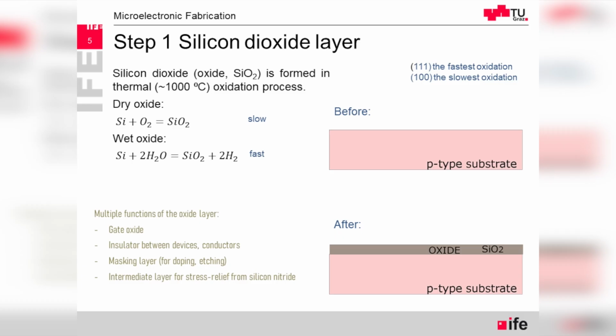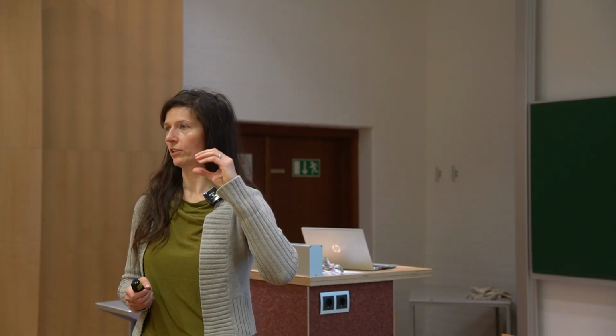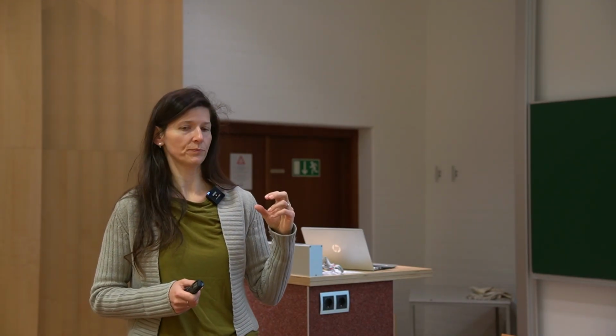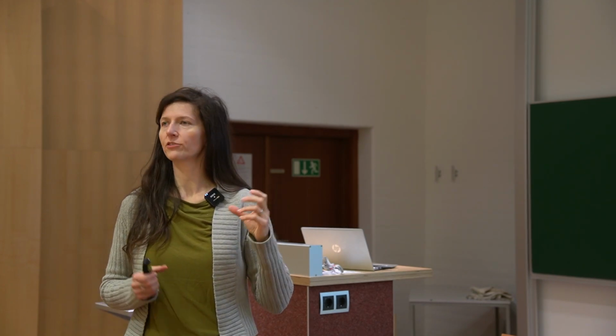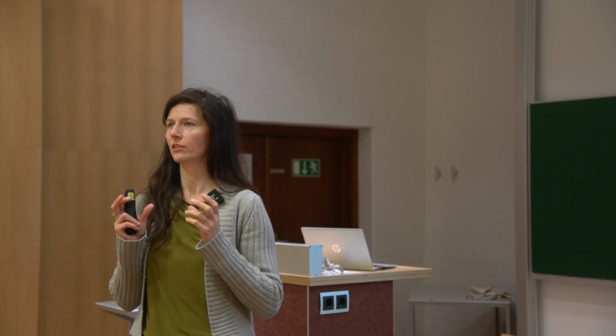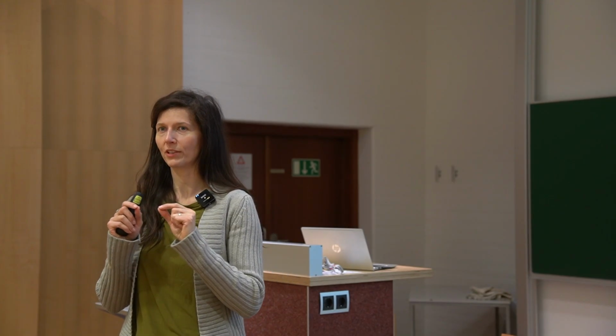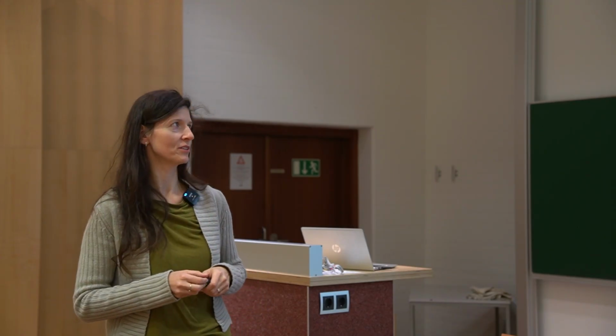There is also a different type of passivation used in between the metal layers, which is not silicon dioxide, it's silicon nitride. Different materials have different mechanics, different stress and response to temperature. In order to have mechanical integrity, if we had the silicon nitride directly on silicon, that would not be good. The silicon dioxide forms a nice intermediate relief layer to make sure that mechanically the structure remains stable.